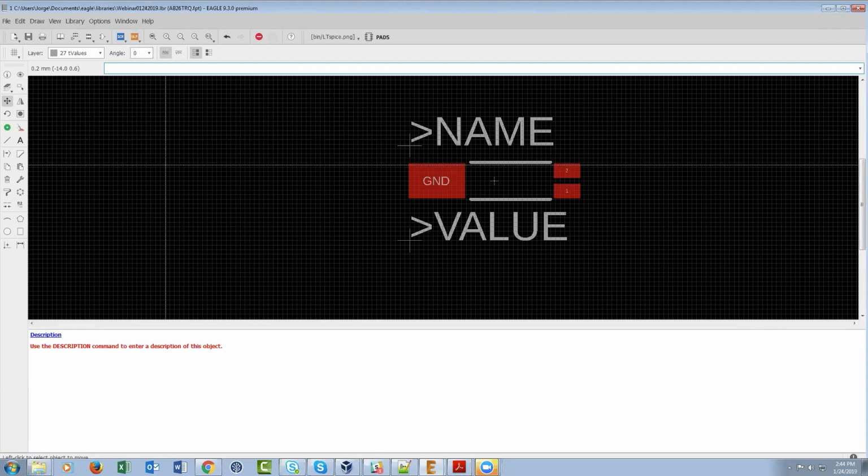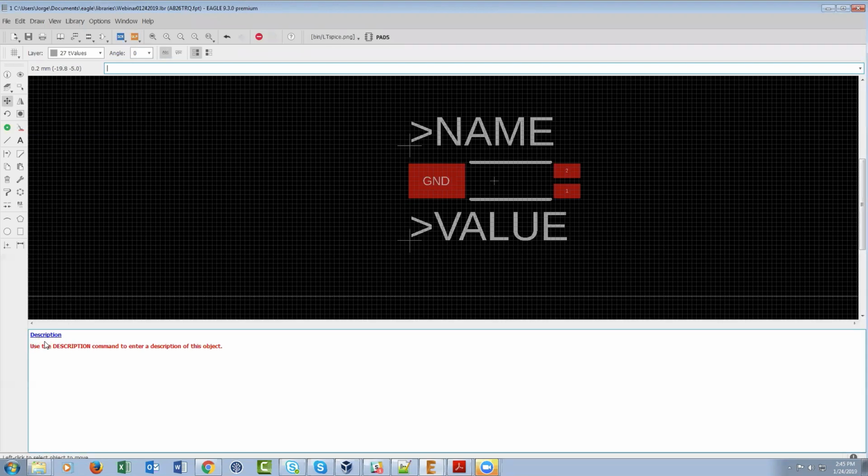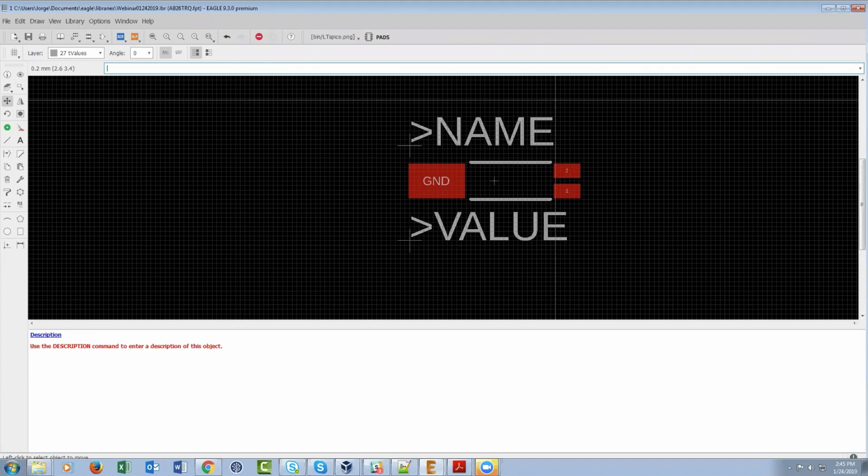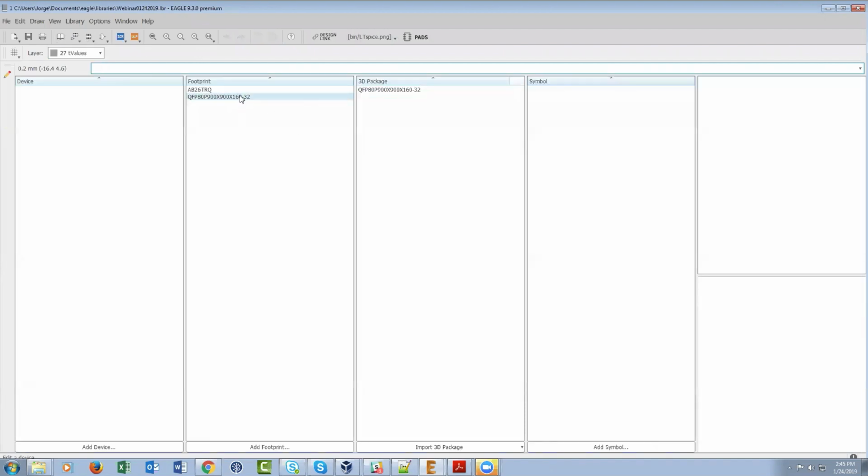Okay, awesome. If you want to put in more detail, you totally could. Definitely description is an area where you can make your life very easy just by putting in links to the data sheet, maybe even a picture of the component, because the description is HTML compatible. It covers a good amount of HTML's functionality. So you can put in links, you can put in different text heights and things like that. Very, very useful. But for a bare minimum, to actually be able to use the part, this is what you need. So we're going to go table of contents view, and you'll see the footprint there.